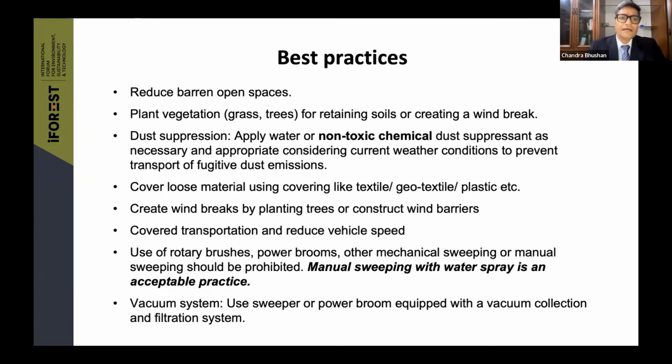As far as a construction site is concerned, an open site, it has to be covered. You have to cover all the loose material, whether you use textile, geotextile, plastic, or any other material. Loose material cannot remain uncovered because the wind will pick up the material and convert it into dust.